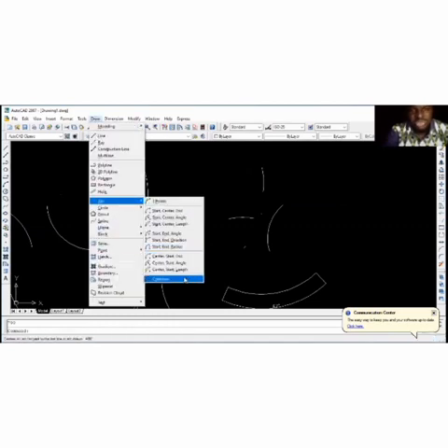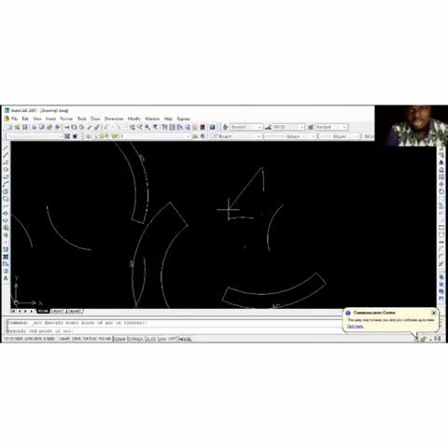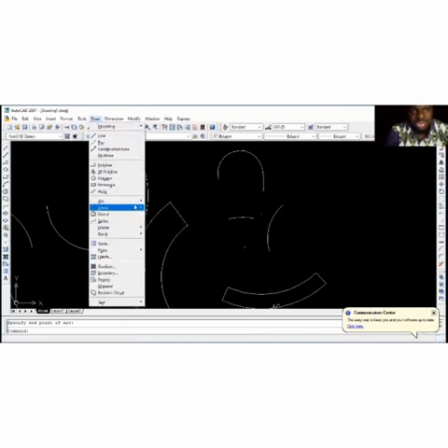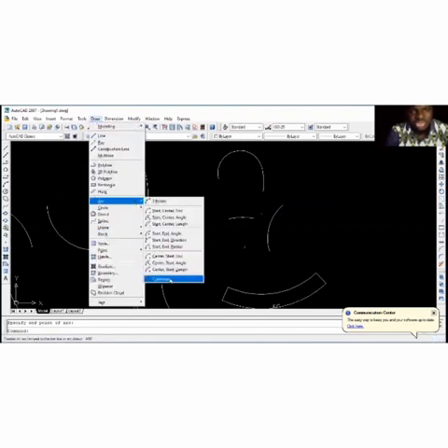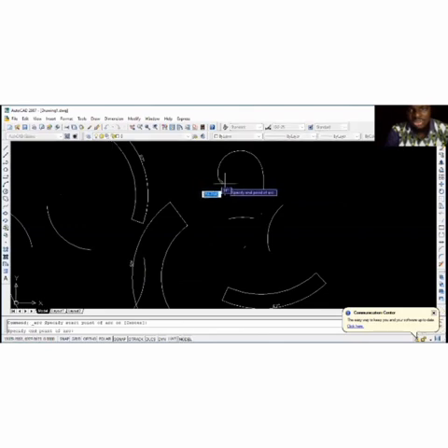So now the last option where we have continue, it means the arc is going to continue from the previous arc. You click on it, you can see it's continuing from here. You click here. When you come back again, and then you come here, click on continue. It will continue again from where it stopped. You can see it's continue. You can decide to come this way, and then that is it. So those are the various options that we also have for the arc command.